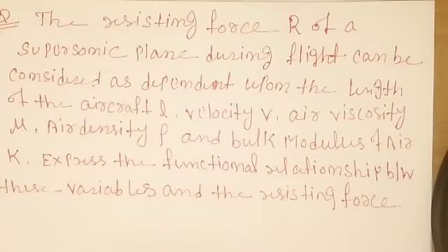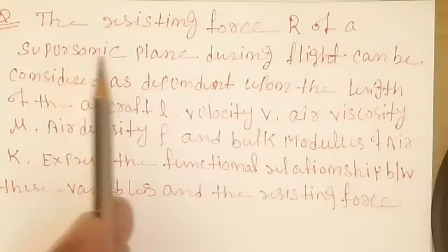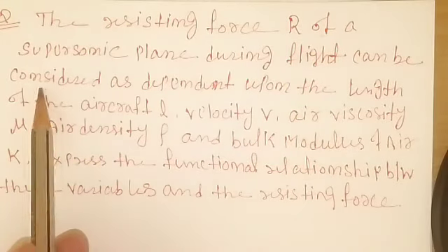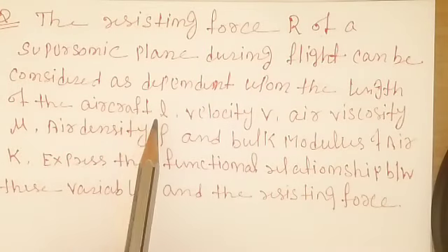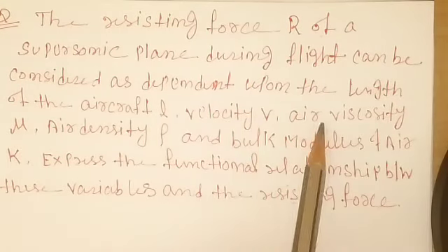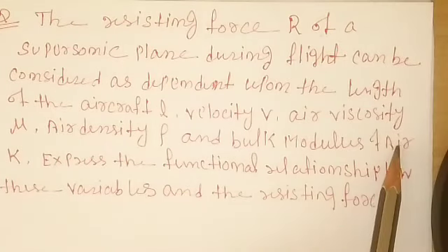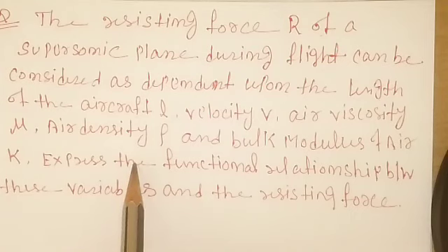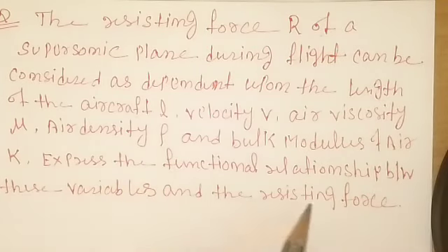So here you have one question I have taken. The resisting force R of a supersonic plane during a flight can be considered as dependent upon the length of the aircraft L, velocity V, air viscosity mu, air density rho, and bulk modulus of air K. Express the functional relationship between these variables and the resisting force.